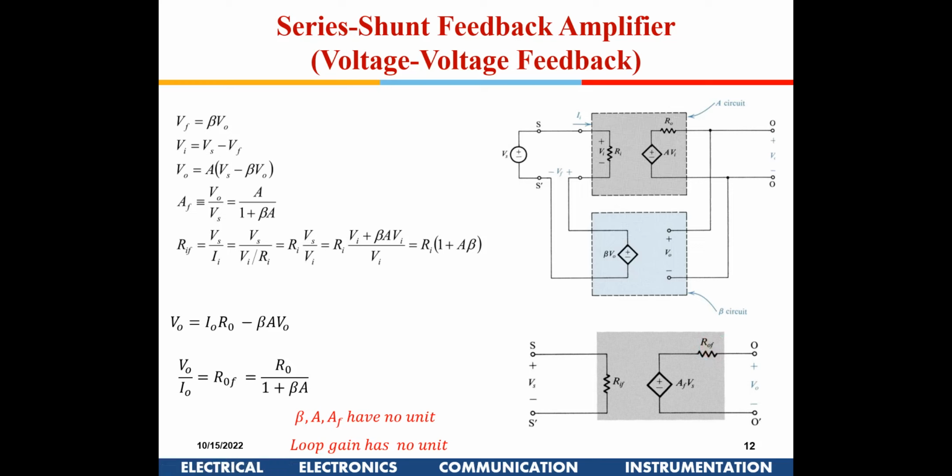Correct. Sir, one doubt. You told that by just looking at the output, it is visible that output impedance should be decreased. I didn't understand that looking at the circuit. Can you explain that? If you are taking a parallel connection for your feedback network, then when I am applying a voltage here, if there is a parallel path, it will decrease the voltage, decrease the impedance, right?